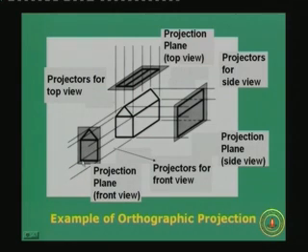Also from the front view, you typically have a cross sectional view where you have a square and then a triangle on the top of the cross section as you see from the front. From the side, of course, you will have two rectangles side by side adjacent. Okay. So, these are simple examples of orthographic projections of top view, side view and front view. Given an object which is very regular in terms of a geometrical shape, I am sure you should be able to draw the corresponding side views.